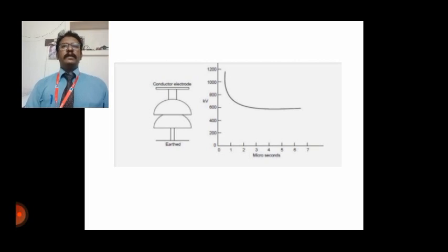breakdown voltage is not less than 30%, which is a nominal value, below which is the voltage withstand level of the equipment to be protected. This has to be emphasized. So even though the rod gap is the cheapest one, it suffers from major disadvantages. That is, it does not satisfy one of the basic requirements of lightning arresters actually listed in that list. It does not interrupt the power frequency follow current.